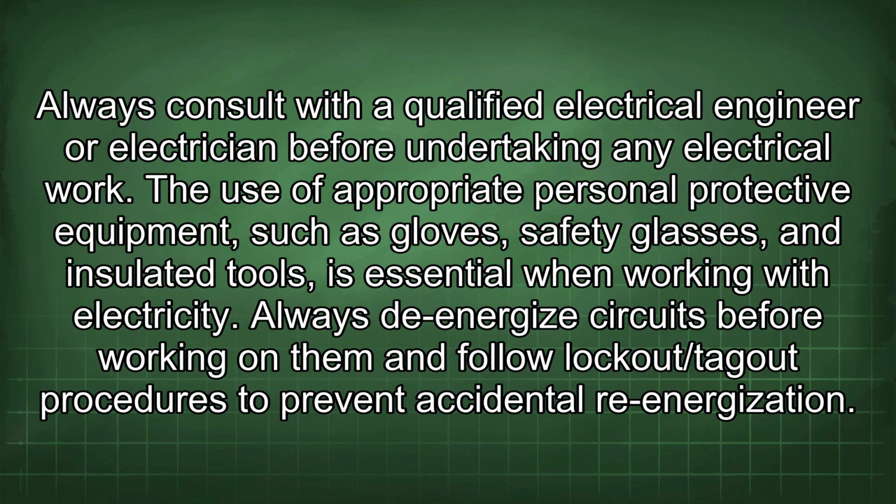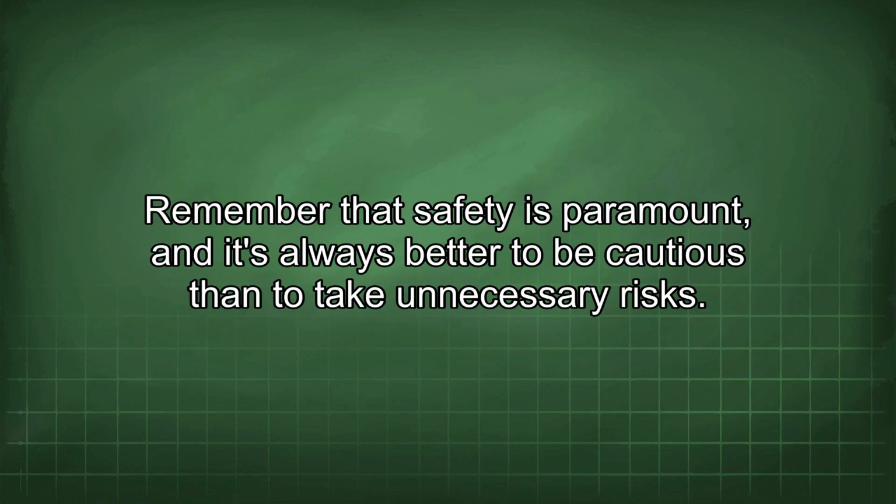The use of appropriate personal protective equipment, such as gloves, safety glasses, and insulated tools, is essential when working with electricity. Always de-energize circuits before working on them and follow lockout/tagout procedures to prevent accidental re-energization. Remember that safety is paramount, and it's always better to be cautious than to take unnecessary risks.